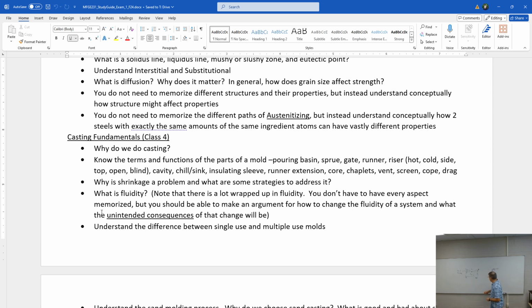And if you remember, there were all kinds of wacky things you could do. I almost knocked the chalk tray off again. Very gentle on the chalk tray. So as you cool the material down, you can drop it straight down really fast, get a hard brittle material. You can drop it down and then oscillate it for a while and then cool it slowly. You can cool it super slowly, that's bad material, don't do that.